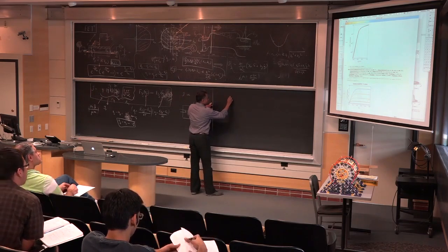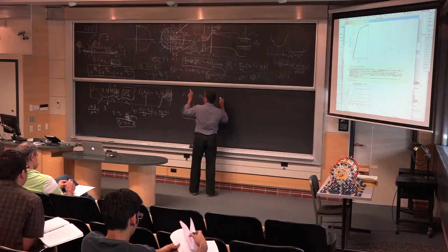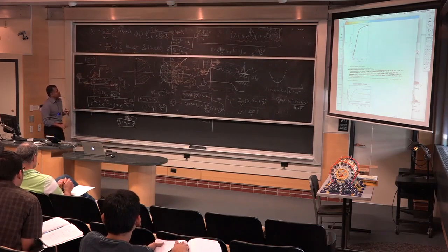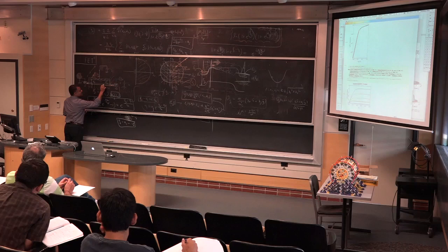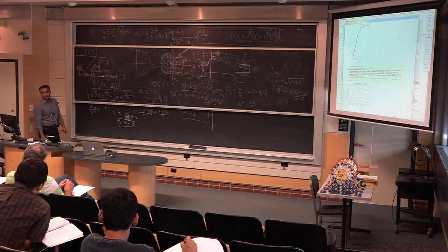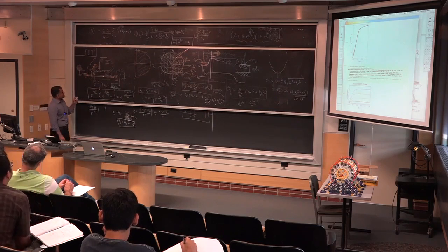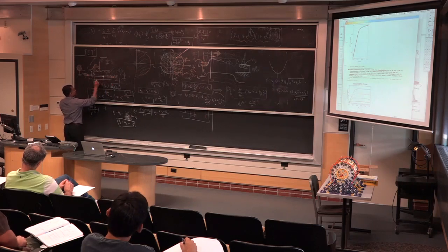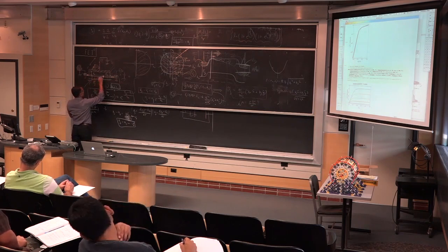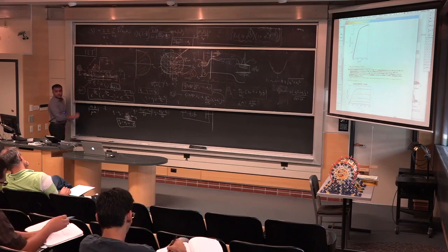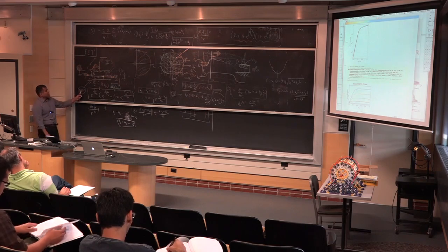Okay? The old picture of the transistor looks like this. So let's go back. I've already drawn that. It's actually a very nice picture too, but it's completely classical. You'll see now. So the transistor, again, we are trying to find what's the current at any point. And what Shockley says is, look, I'm going to go to a point here, and this is my length L, this is my x-axis here. I'm going to ask the question, what is the carrier density at that point x? What is n of x? Sheet carrier density. What's n of x?